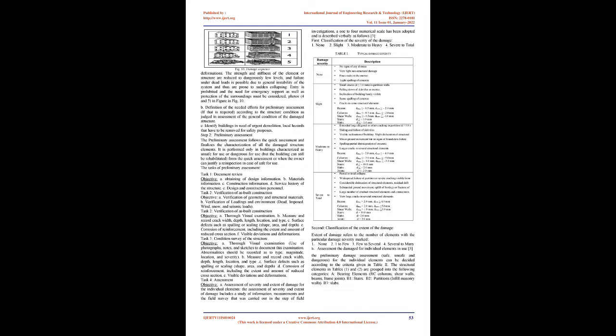3. Unsafe for use, dangerous for use, extensive cracking or loss of material with gross permanent local or overall deformations. The strength and stiffness of the element or structure are reduced to dangerously low levels, and failure under dead loads is possible due to general instability of the system and thus are prone to sudden collapsing. Entry is prohibited and the need for emergency support as well as protection of the surroundings must be considered. Photos 4 and 5, in Fig.